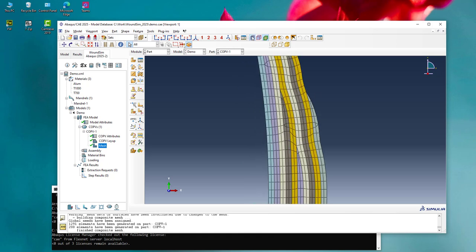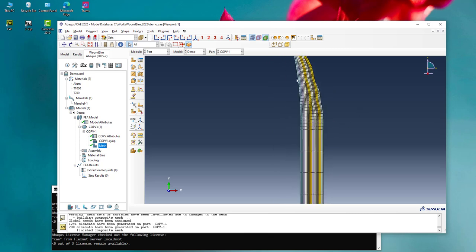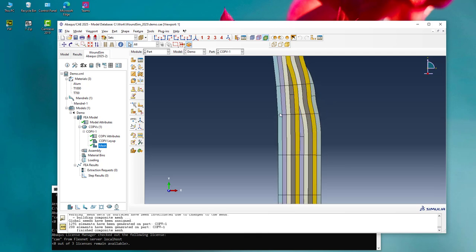All right, so overall we're looking pretty good, but if you've ever plotted stresses, let's say along the cylinder and along the dome, what you'll see is lots of oscillations where these layers are terminating, and then you get down here and it's nice and smooth, but there is some transition area here. So what this algorithm is doing is we ask for a certain number of partitions, and as soon as it finds a partition where there are no partitions like this inside of it, it's going to mesh it with the coarse mesh.